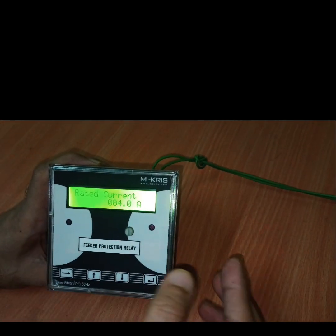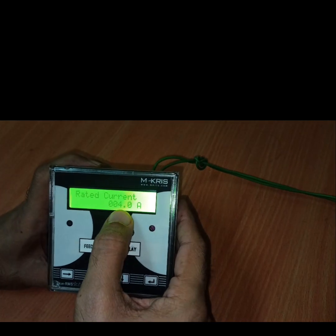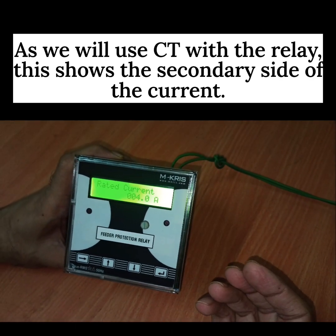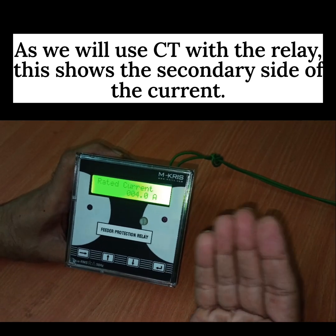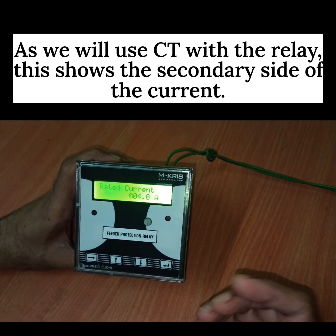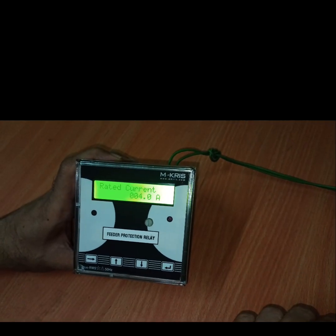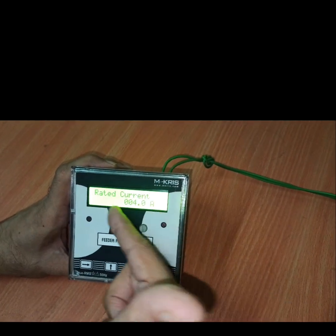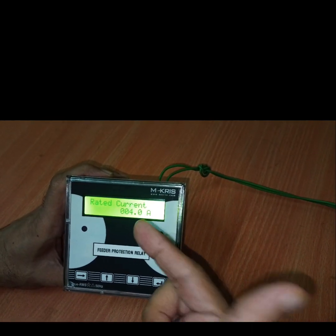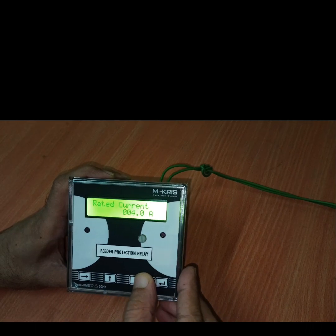So this is the rated current. Rated current can max be set up to 5 ampere. Because we will be using CTs normally with the relay, this shows the secondary side of the current. So CT could be of 200 by 5, 500 by 5 or any rating, but this will be the secondary side of the CT current. So this is the rated current.